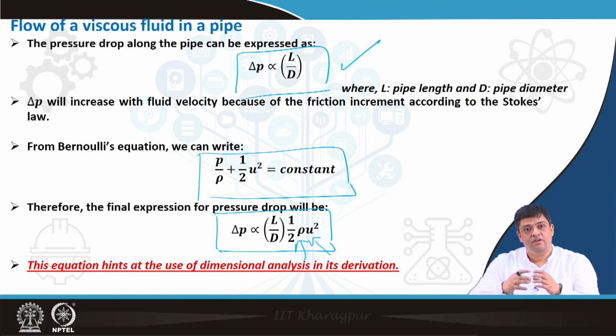And if you need the velocity to be very high, that means the length becomes a bit larger, otherwise you will have a very steep dam. If you have a very steep dam, it has its construction issues. So, all these factors have to be optimized before this very simple term of change in pressure can even be calculated.